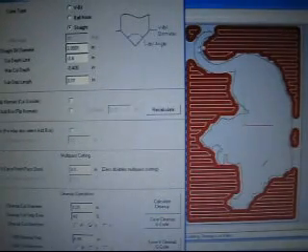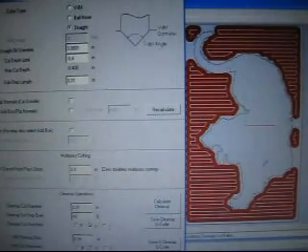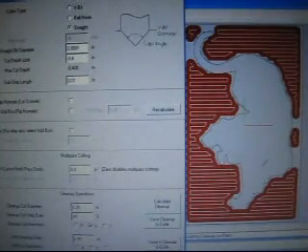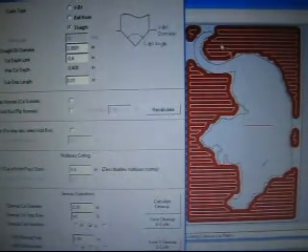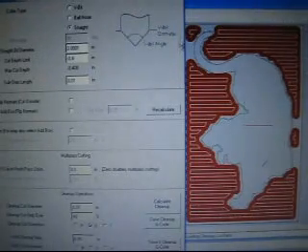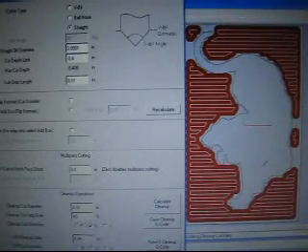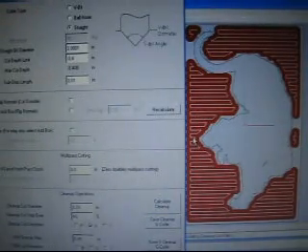This area at the top of the tail, and around this side of the tail, and around here this body, and around here this body. We're not getting that machined. So what we have to do is enlarge the perimeter, the bounding box for the tiger. We've got to enlarge this outside rectangle for this thing to work.